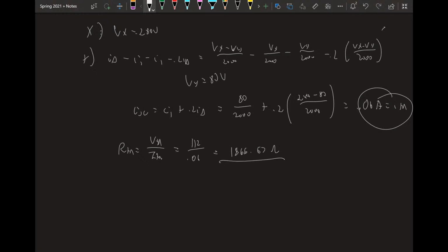Okay, so let's get cracking. Let's paste this back in again so we can see our circuit. And remember, we have to deactivate all independent sources and then apply a test voltage. So let's start deactivating sources. We only have one independent source in the network. That's this voltage source. It goes away, replaced with a wire. Right? We can't deactivate dependent sources. And then we need to add a test voltage here, V test. We want to solve for I test.